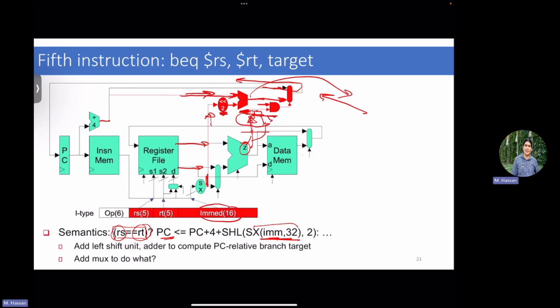This also makes this fetch circuitry a little bit more complex, because right now I added all of this green thing for the branching. But now for my jump, remember that in a jump, you don't have an offset that you add to the program counter. You just take the jump address directly, sign extended, shift it by 2, and load it to the program counter, right? So again, remember this is the logic we have. You take these bits, which are your immediate value. Well, this one, sorry, you shift left by 2 to handle the 4-byte instruction.